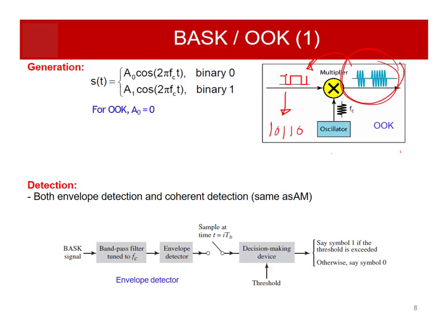It can be either envelope detection or coherent demodulation, depending on the type of amplitude modulation scheme that we use. You can remember that depending on the mu, you could use either envelope detection or coherent demodulation technique, or simply demodulate the signal by multiplying it with the carrier once again. It's up to you. So the first step is going from here to here, which we can do obviously with envelope detection.